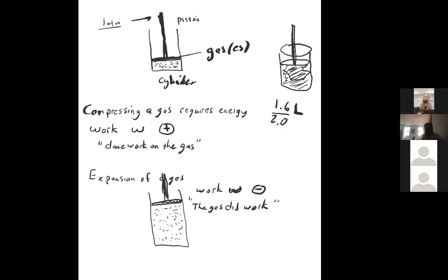But essentially what happens is when a gas expands, it loses energy. The gas loses energy, and the energy goes out to moving this mass. So if the cylinder is compressed, work is positive. If the cylinder expands, if the gas expands, then work is negative. Okay? So 2 sign conventions.